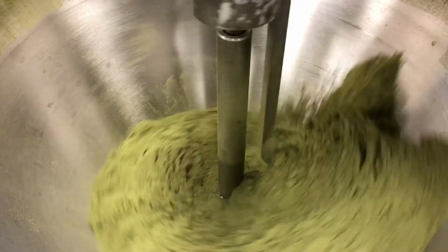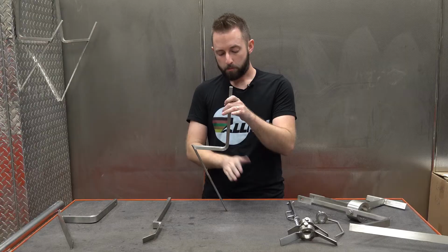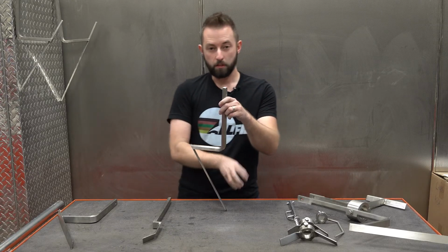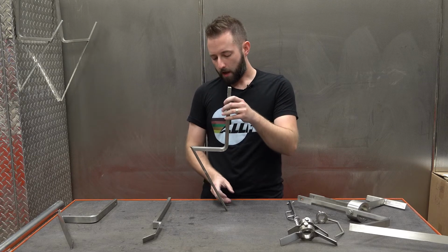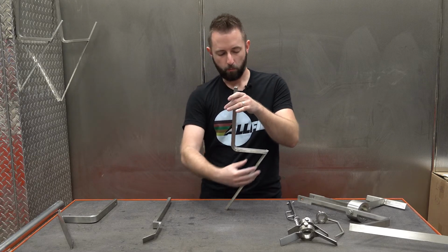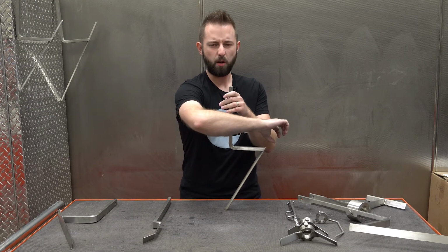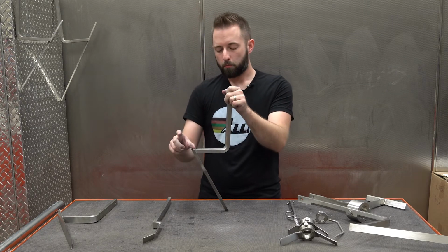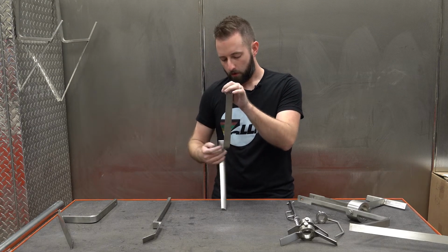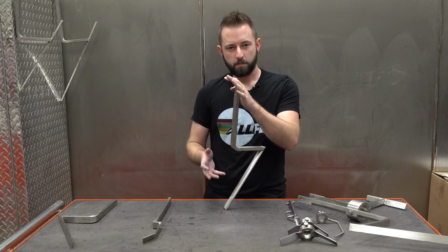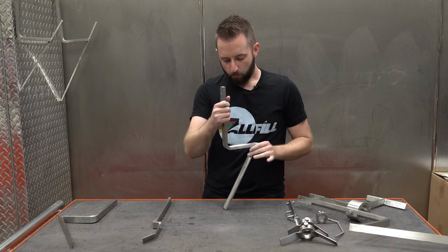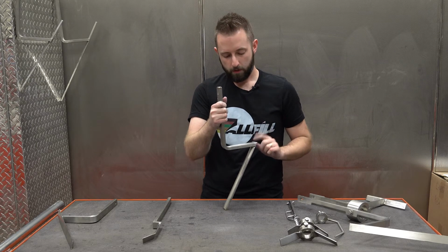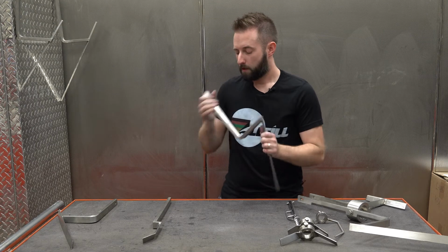The whole mass will spin. So instead of product collapsing in on itself, the entire piece is just pushing around in a circle and never feeding to the auger. So what you'll end up having is as this advances, product will build up, it'll catch that upper ear, and that upper ear is helping to drag that mass of product around the hopper. By removing the upper ear, we're able to help reduce the amount of mass turning that we have inside of the hopper. Some products, this still doesn't alleviate that fully, but there is a lot of products that have that issue. This tends to really help with the problem.